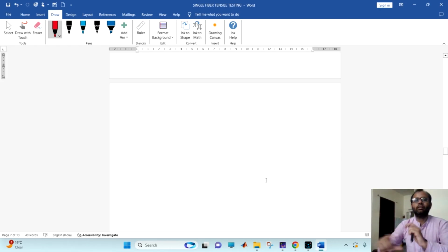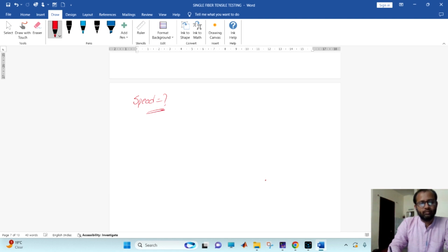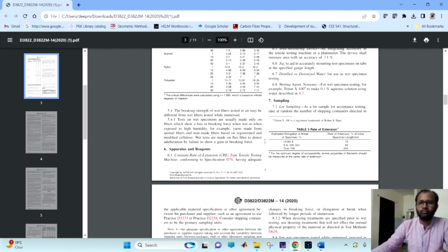Now I have to explain at what speed we have to do the testing. That is the last part. For this we go to the ASTM, that is D3822, where we come to the rate of extension.